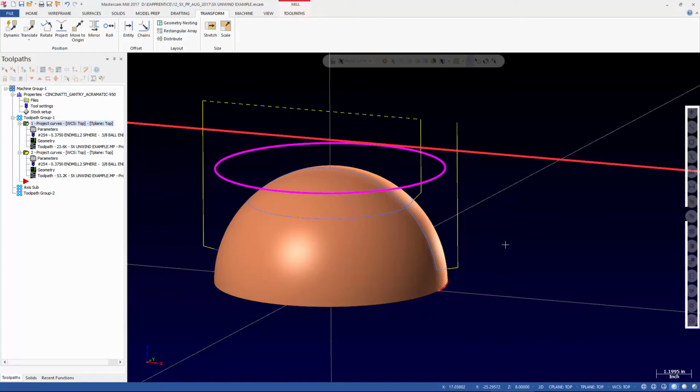And a lot of it really depends as well on how much full 5-axis motion you guys cut on a daily basis. Out in the real world, when I'm driving 5-axis, 90% of what I do is 3+2. It's the pretty rare part where we actually need full 5-axis motion. Now, maybe not.